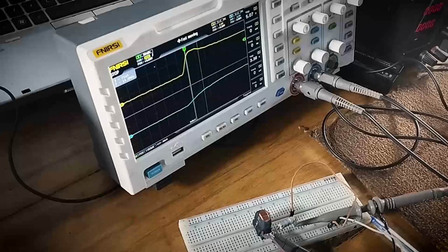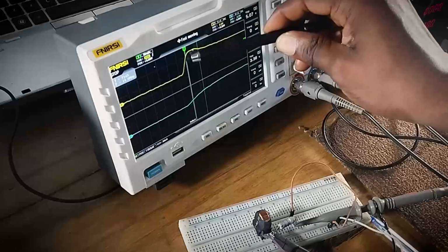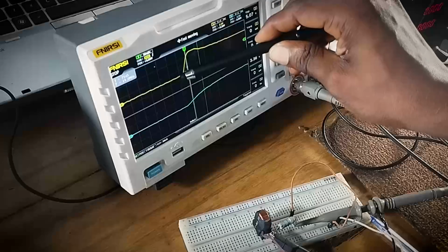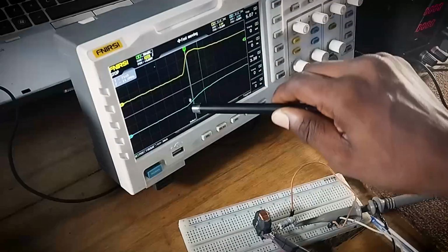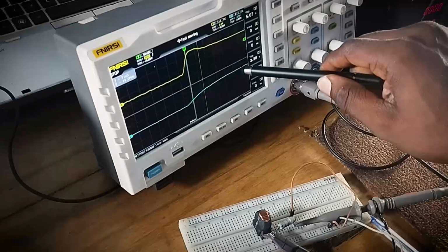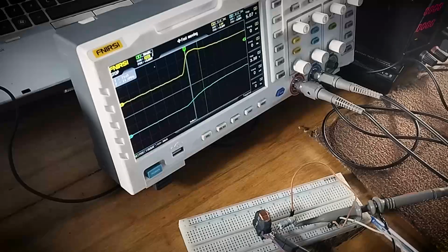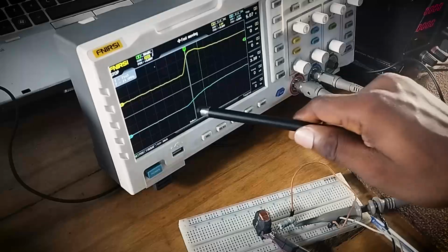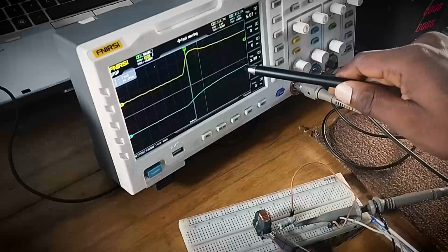Now, the signal coming out from the 555 timer isn't automatically instant. It has its own delays too. But if you watch down here, you see that the inductor delays further. So you can see the property we talked about for inductors: it resists change of current flow. There's no instantaneous change for inductors. Once it senses that change, it gives off a resistance and causes the change to happen gradually. So you can see that move here.